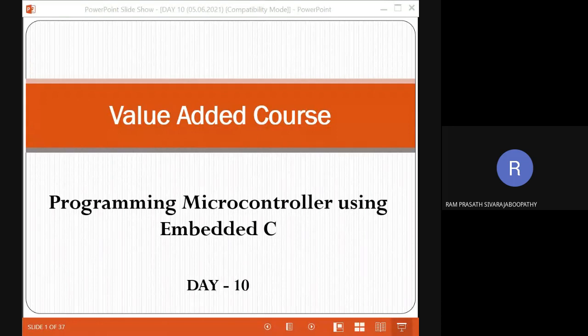Yes, synchronous protocol. It is using a serial synchronous protocol. It uses that protocol so that you will be transferring bit by bit information. It gets into that particular IC and is converted internally into 8-bit data. The serial data it is receiving, it converts into parallel data. So based on the data we are writing, it is going to generate the scanning process and everything.